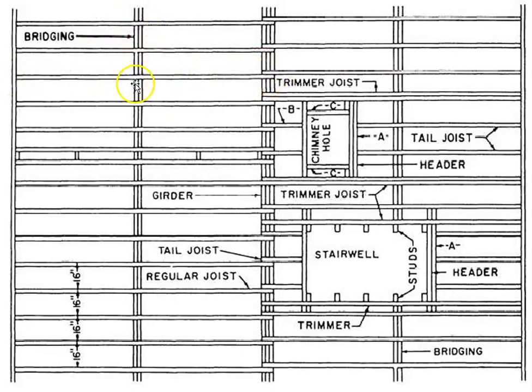We see the bridging or blocking, 2 different terms there, bridging or blocking. Typically they'll put it over the girder at the end of the joist, and they'll also put it mid-span. And there are many other pieces involved in openings, or not many. A lot of the terminology in openings in the floor are also used for openings in walls. So trimmer joists, or just trimmers at least, you'll see that when it comes to windows as well. I'm not going to go into the detail here. I just want to kind of stay focused on the bigger picture right now.